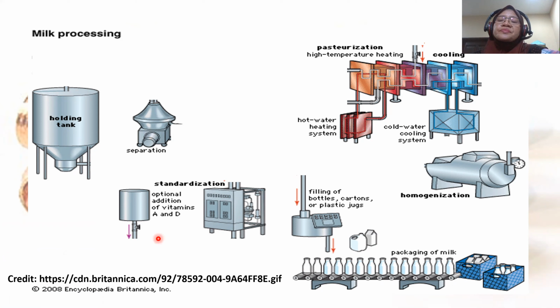separator, tank, small tank for micronutrition ingredients. This unit is something like dosing, okay, to dose the ingredients for standardization of milk. Pasteurizer here, which is plate heat exchanger. There is a cooling system here, homogenizer, and this is a filler machine to fill the milk into the bottles.